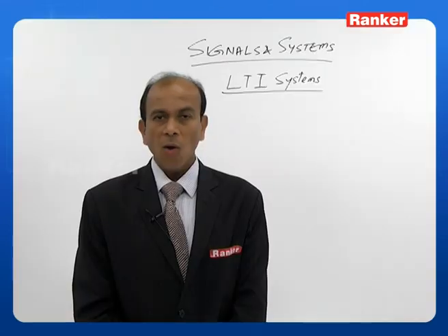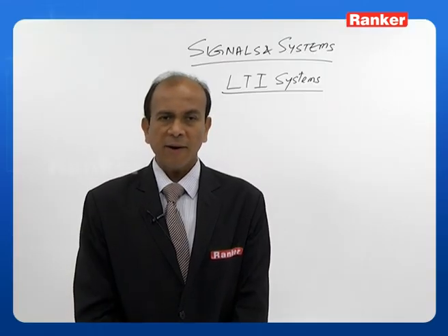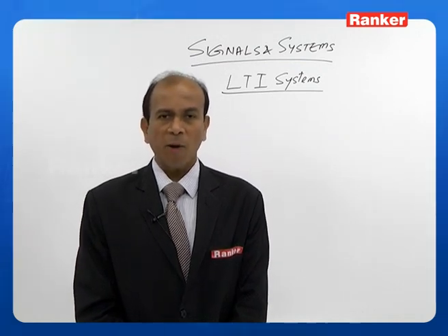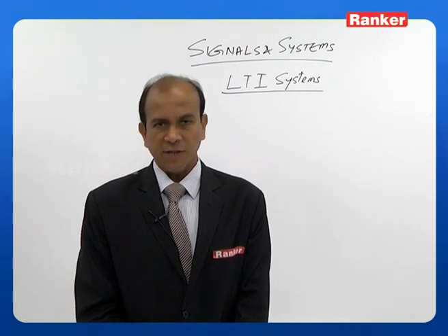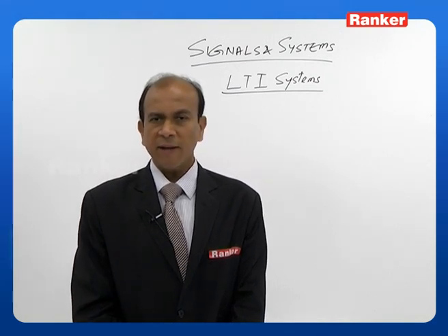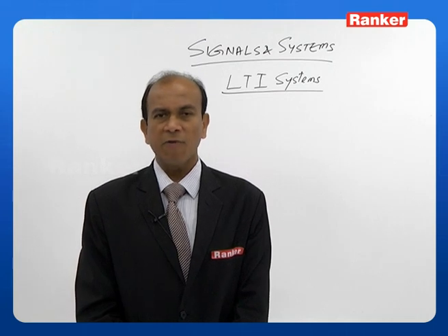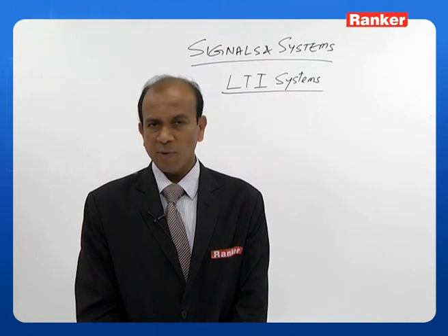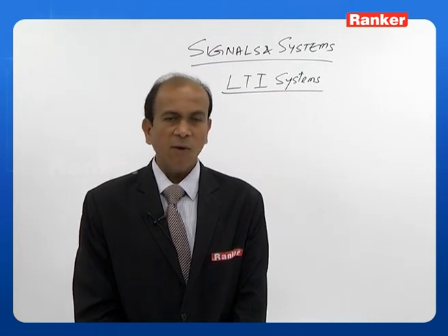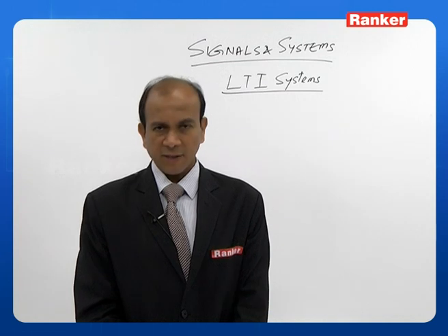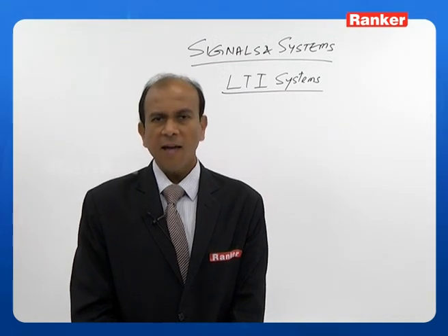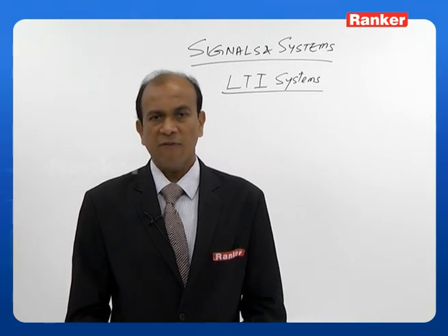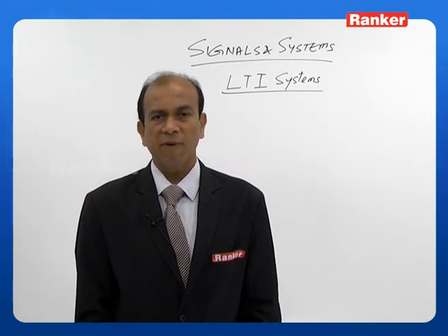This is very important. If you look at the periodic signals, they are all power signals, and non-periodic signals are all energy signals. That's why Rayleigh's power theorem always talks about P equal to 1 by T, where T is the period. The integration is between those periodic limits; that is the power signal. A power signal is generally a periodic signal, and an energy signal is a non-periodic signal. This is how we can classify different types of signals based on the type of energy available.